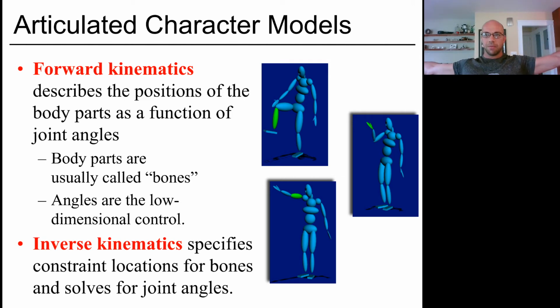Now, if I want to know the position of my fingertip as an XYZ position, I have my body in some basic rest pose, is usually what it's called. Well, now when I bend my arm and my finger and my wrist, I have different angles, and all of these things essentially are inducing different rotation and translation matrices all the way up and down my kinematic chain. And so if I want the position of this fingertip, what we're going to see is that I've got to multiply all those matrices together. So that process is called forward kinematics. So given things like joint angles, the output of forward kinematics is the actual position or pose of the 3D character.